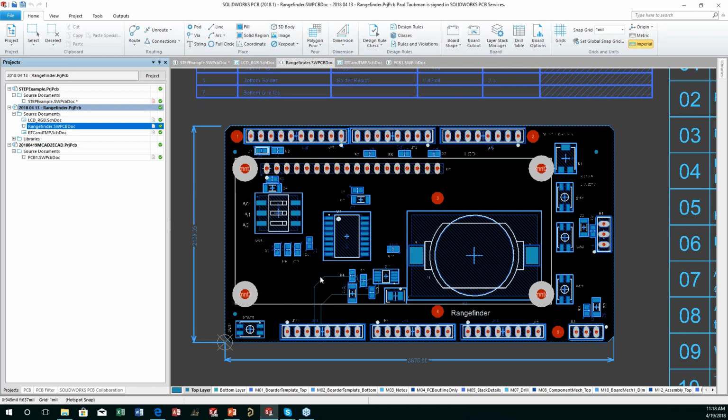And if you've got something that's got 8 layers and 1,000 pins on it, you can't just simply move it or nudge it over a little bit. There's a lot of work that has to be done. They effectively have to tear up all the routing, move it over, and then reroute it. So we don't send the stuff back and forth in a routed state. The routing is done after everybody is happy with the component placement. So that's what I've got over here.